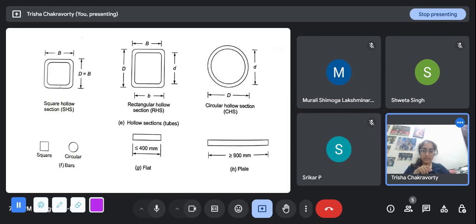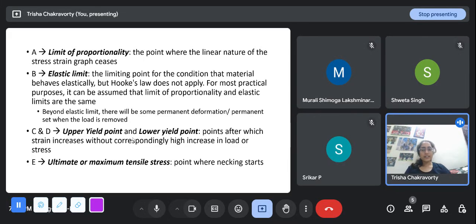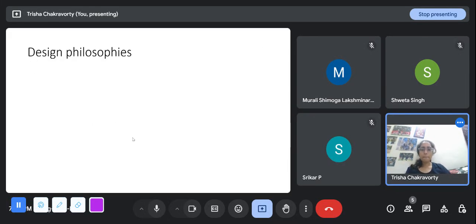The dimension going into or out of the plane is the length. That is generally much higher than these dimensions, which, if this is 450 by 400 millimeter, would probably be something like 50 millimeter or less. So these are slender structures, and that is why buckling becomes very important.